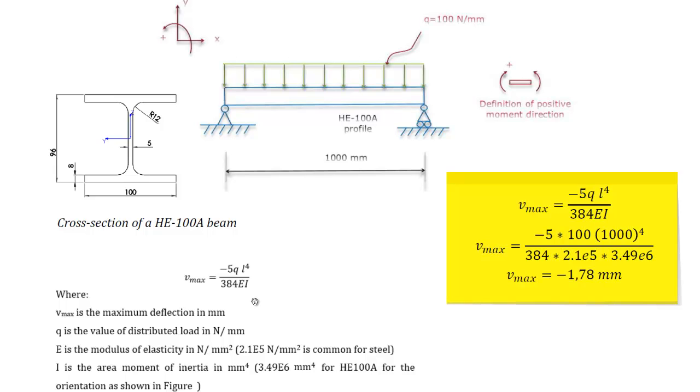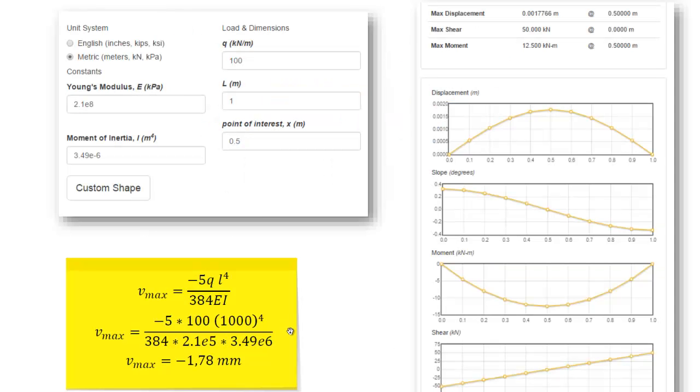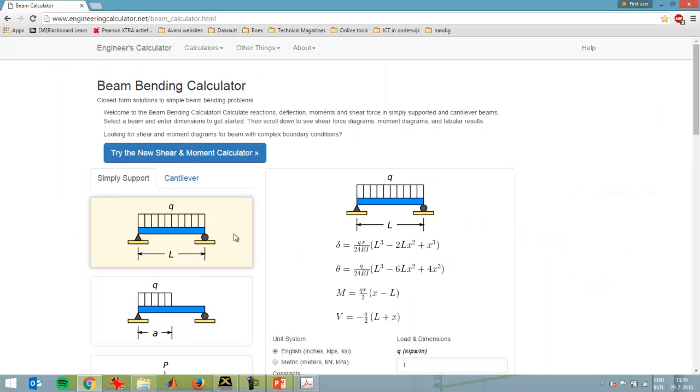This tool does give you the maximum deflection of a beam, but on the other hand, Autodesk Force Effect allows you to create your own beam structure, whereas this tool, as I'm going to show later, does not give that opportunity. So here you see the calculation that is done. You have to pay good attention to the units to get the exact right results. Here you see the hand calculation version of the deflection that I calculated by entering all the values in this equation. And now I can show the online calculator tool.